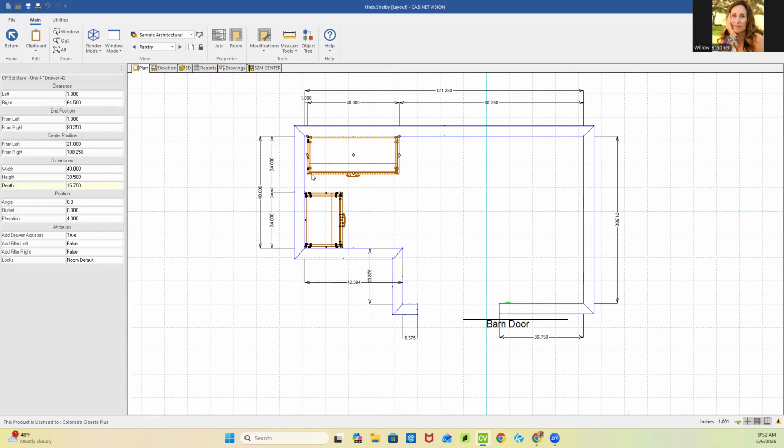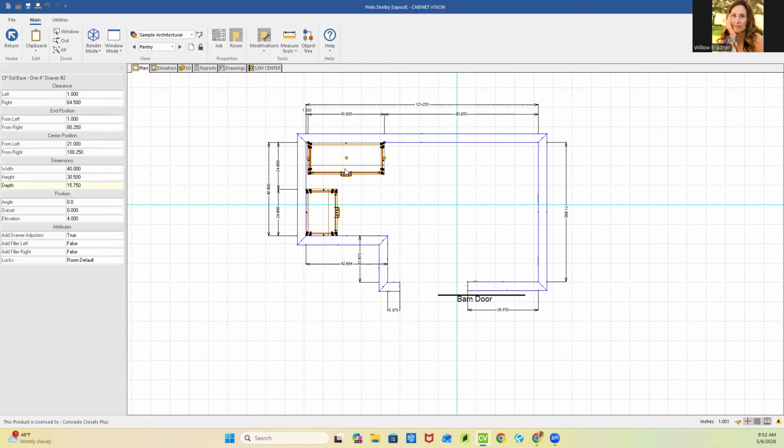It also allows this entire run, anything that's connected to this cabinet running down the length of this wall, some flexibility and breathing room. So if this measurement is off by a quarter inch, we're not smashed between two walls, because I like to leave maybe 3 inches or something, right? So I'm going to go ahead and add 2 inches. So now my cabinet is 3 inches off of the opposing wall.